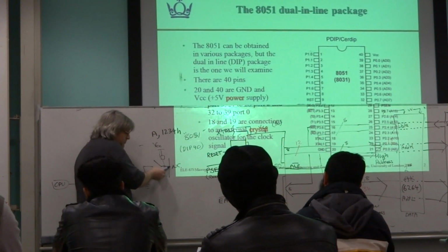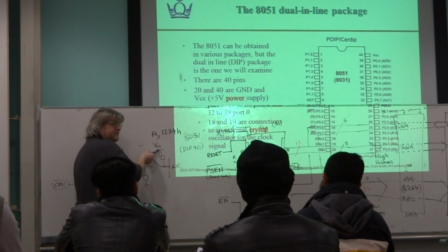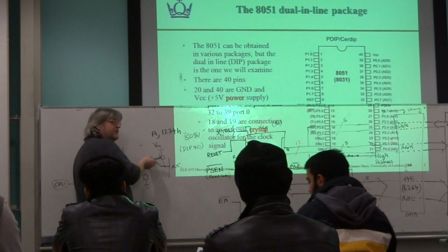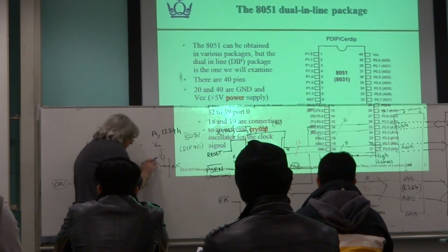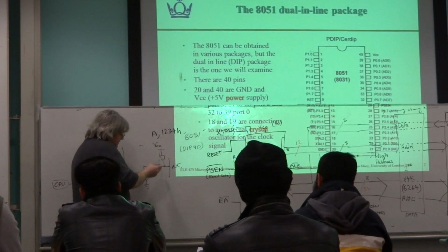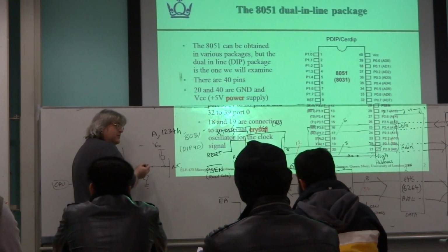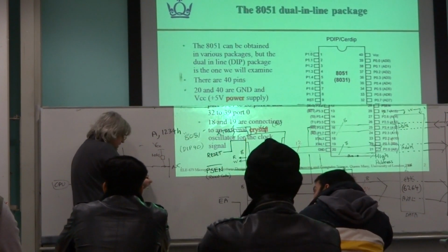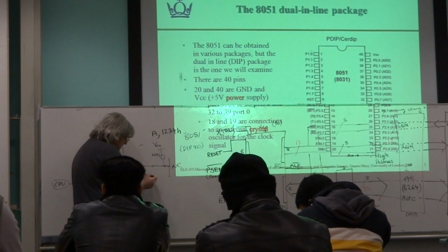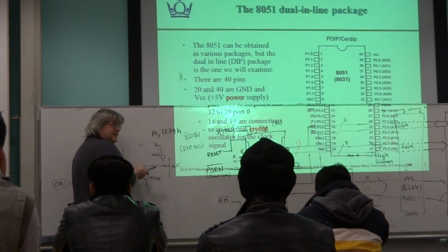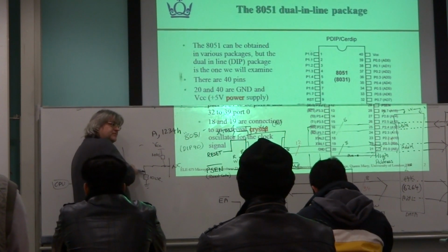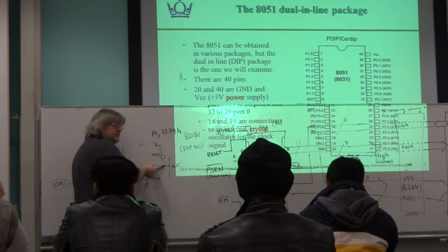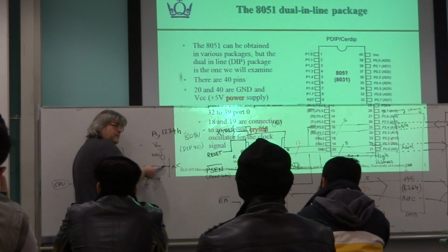And so if you sample this point here now, there'll be a small voltage drop across here, but it's almost at VCC. It's no longer floating. But when you close this switch, now depending on the values of R you choose here, normally you choose this to be quite big, so this might be, say, 10K, and this might be ground or very close to ground, let's say this might be 100 ohms or something. Then, based on your knowledge of potential dividers, almost all the voltage is dropped across here, virtually nothing's dropped across here. This potential now becomes almost at ground.